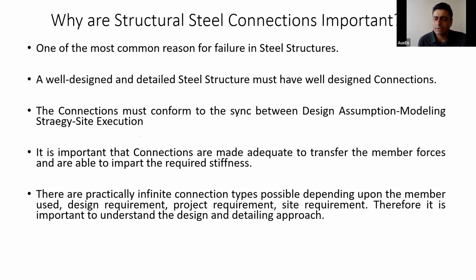Mr. Asad is saying progressive collapse, if connections are not properly done, may lead to structural collapse. Right. So what I was telling in the first point, that most of the common failures in steel structure is due to failure of connections. And when connections fail, generally they fail without giving you sufficient warning. And mostly in steel structures, they lead to what is called a progressive collapse.